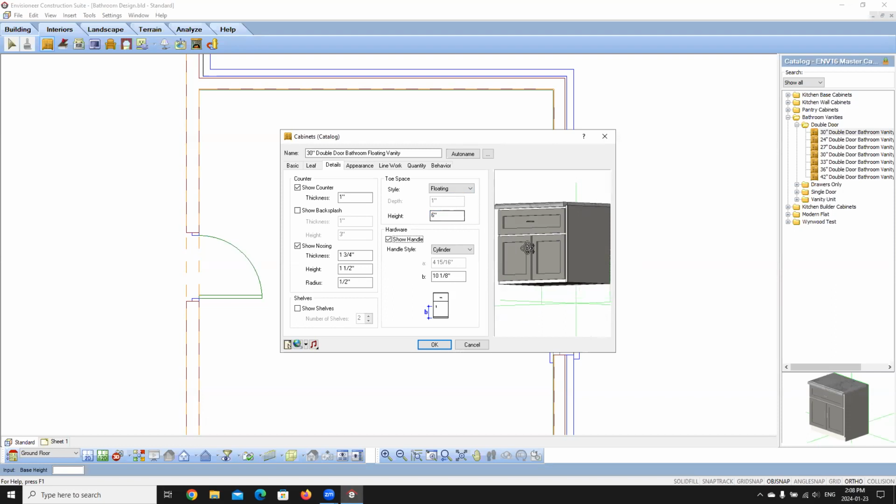And then I'm just going to press tab. That's going to reduce the height of the cabinet doors themselves because I need to take that into consideration. I still want it to insert at 2 foot 8 inches high, but I want to make sure that I have enough room so it's floating off of the floor itself. So by adjusting that option, I've given it that 6 inches of clearance from the floor to the bottom of the cabinetry. We can also control the hardware.